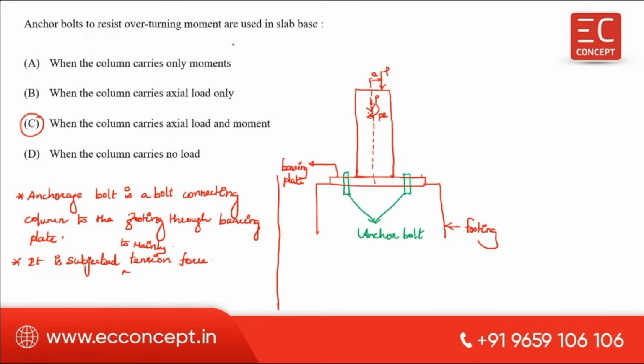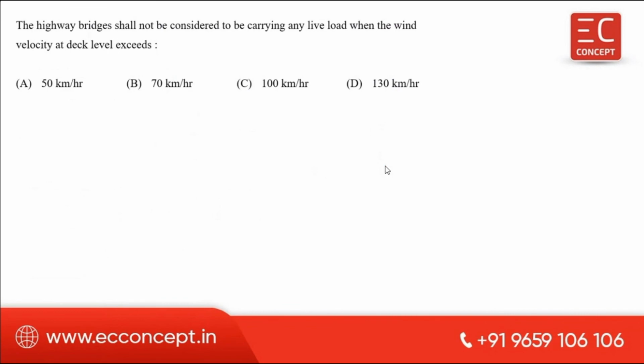If the column carries only axial load, that means a concentrated load, then the anchorage bolt only carries axial load. If there is an eccentrically loaded column, that means if there is any moment, then the anchorage bolt also carries that moment.